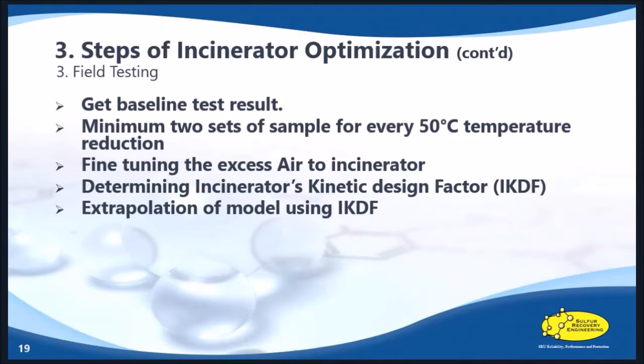Before field testing, the client must recalibrate or re-verify all related flow meters, thermocouples, and analyzers, because this is the data we are looking for to create a model at the end, and models are only as good as the data. So this is a very important step before we go ahead and start field testing.